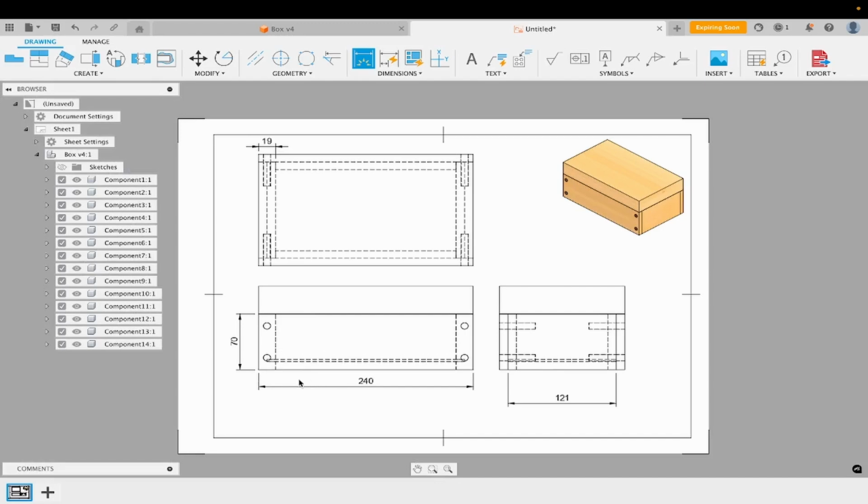Have you got enough on there to make the box? Length of the front, height, thickness. Yep, side, the length, the height, the thickness. Yes, the lid. So make sure you've dimensioned your lid so you can get the thickness of your lid there, whatever yours is. The width is the same as from there to there and down. And the length, we might put in the top view here. Actually, we don't need it at all, because if you follow those lines down, it's the 240 as well.